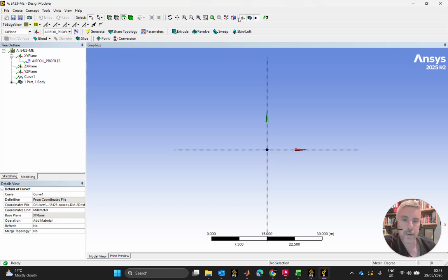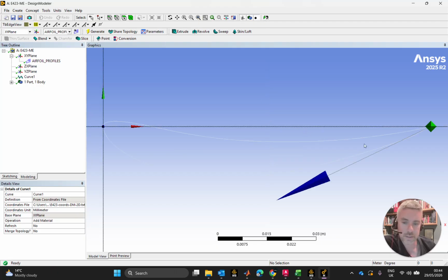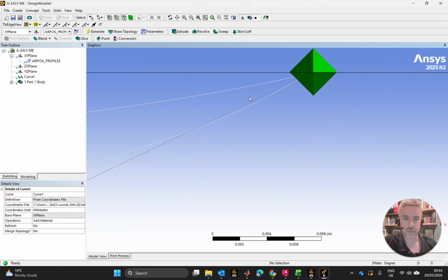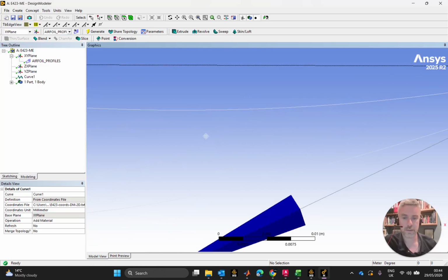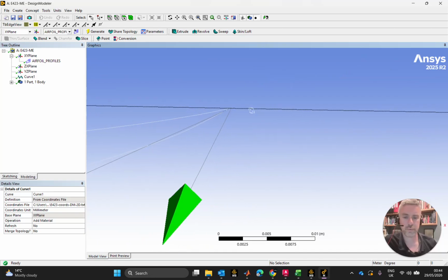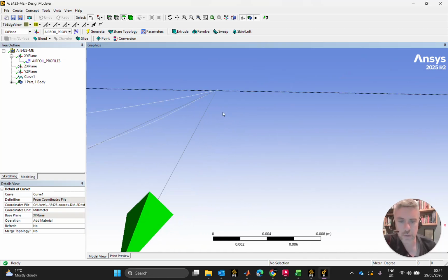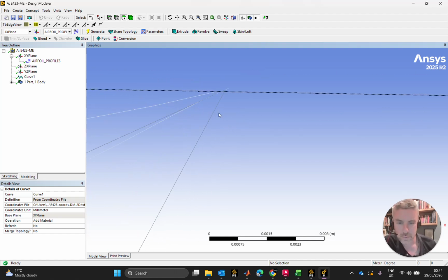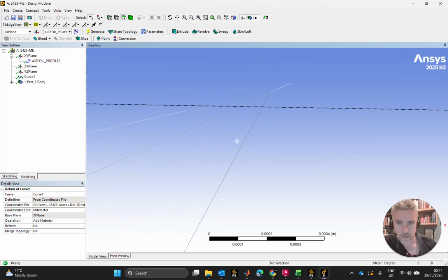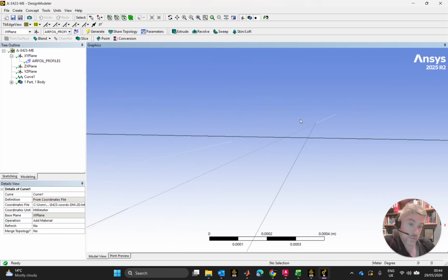Right. I'm going to zoom extent. There it is, and we can just about see the airfoil here. Go into the darker region, it's a wee bit handier to see. I'm going to rotate it round here, so we get this big old vector out of the road. And we can see now that we have a trailing edge that is not closed. I cannot create a surface from this. I can't create a surface on this until I close this edge.